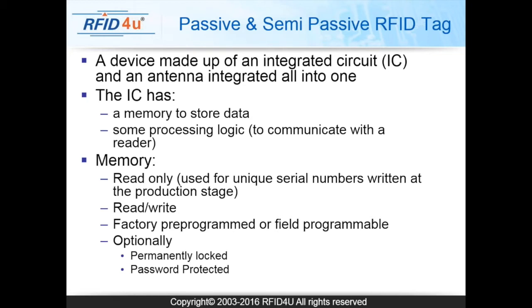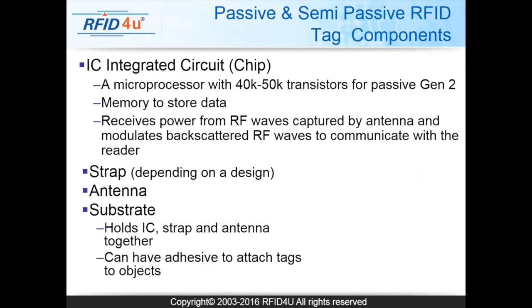We have read-write tags. All the tags following the current Class 1 Gen 2 V2 standards can be written to up to 10,000 times. So that's all part of the standards. Or you can, in fact, have the factory pre-program or pre-write all the tags for you, of course, for a cost. So your decision as to which way you want to go. And optionally, the data on the tag can be locked so that it can't be changed, and the data can also be password protected in the memory so that it would require a password to be able to read the tag or write to the tag.